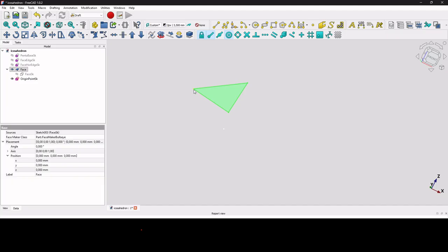The problem is that you need to have a proper working plane, and I discovered that when I wanted to, for example, reorient 3D views that were slightly offside in terms of horizontal line or something like that. So how do I build a working plane? Well, that's pretty easy in a way. What I will do is create a sketch first in order to serve as the basis of my plane.